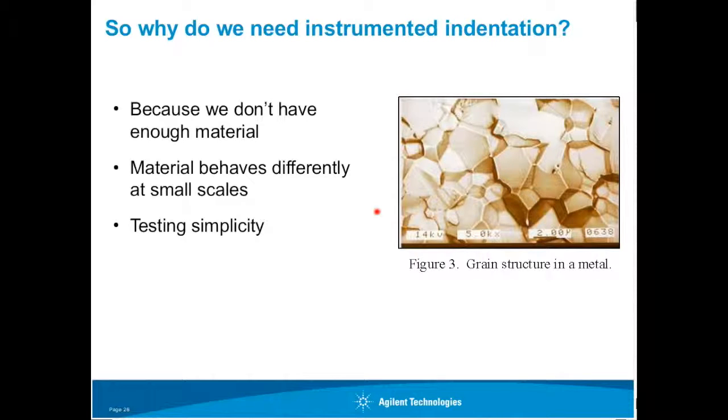That's especially true for plastic properties, and that's because the constraints of the material dictate the grain size of the material, and grain size dictates how dislocations move throughout the material, and that dictates the plastic behavior. So in general, it's important to remember that especially with respect to plastic properties, the material simply behaves differently because it exists in confined spaces. And so if that's how you're interested in using the material, then that's how you should measure its properties.